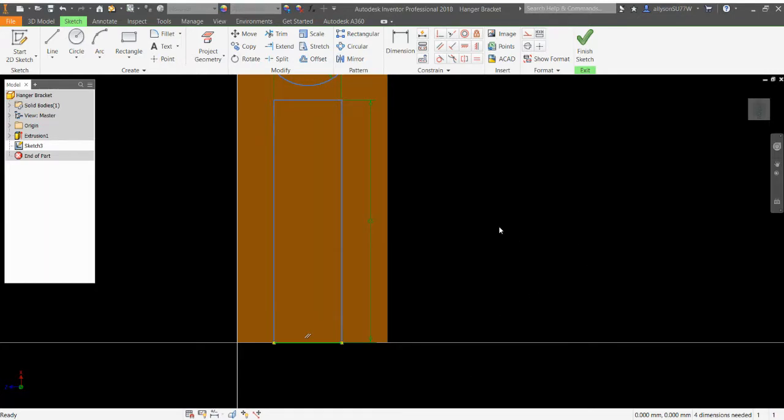So the picture also tells me how far off that keyhole is from the edge of that block. So they're telling me that the total width of this block is 40 millimeters, but this cutout is going to be 18. So again, just doing a little bit of math, if I take 18 from 40, that's going to leave me with 22. And if I take 22 and divide it in half, it means that each section, this keyhole should be 11 millimeters from the outside edge.